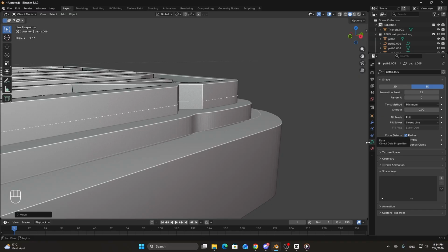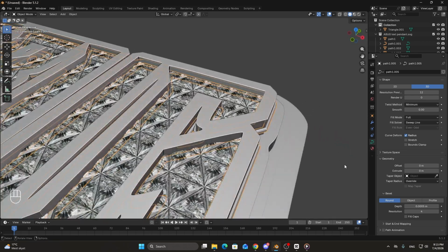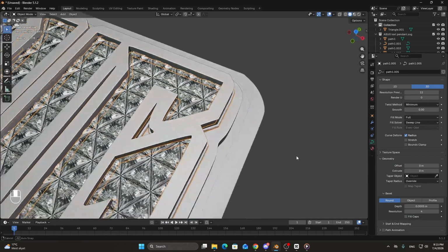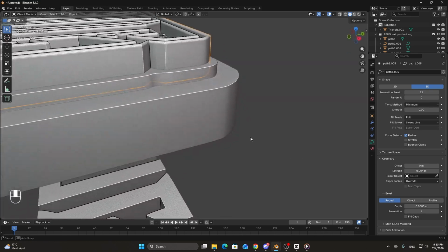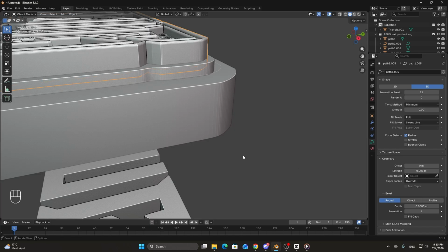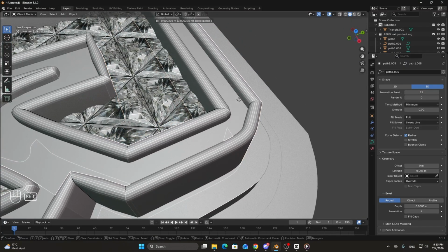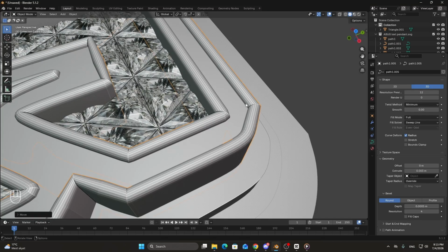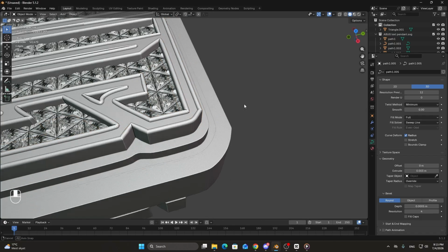Then go into data, go into geometry, make the depth 0.005, I think. Yeah, that's good. And then extrude to like I think 0.03. So hold shift and 0.03. Then move it till the edge is barely above. As you see here, just like this is good.